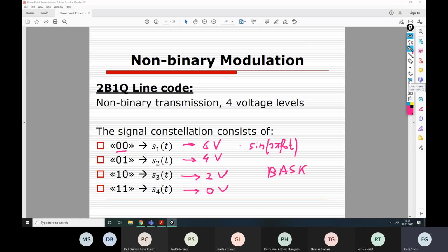So the idea is pretty simple and straightforward. We are going to use more signals, and usually we take the number of signals, capital M, as a power of 2. Well, because from the information theory, you already know that this way, for binary symbols represented by some rectangular pulses, this allows them to carry the maximum information amount, which was calculated as an entropy, if you remember, and that entropy was usually some fractional number. So, for example, let us say 3.21, right? And for that, you needed to use 4 rectangular pulses in order to transmit these 0.21 bits of information. You still used the entire pulse.